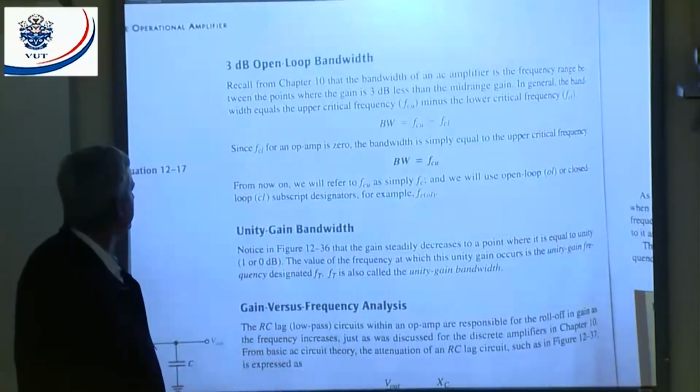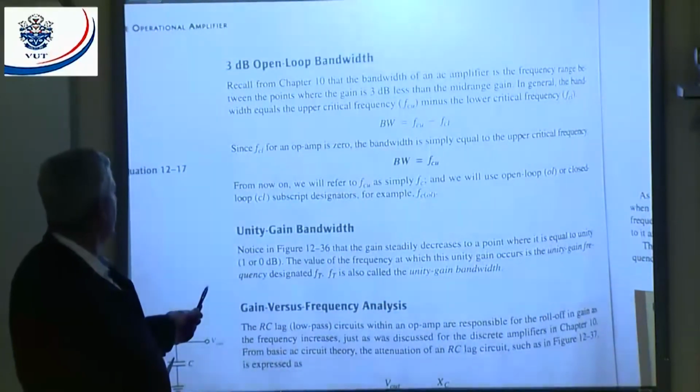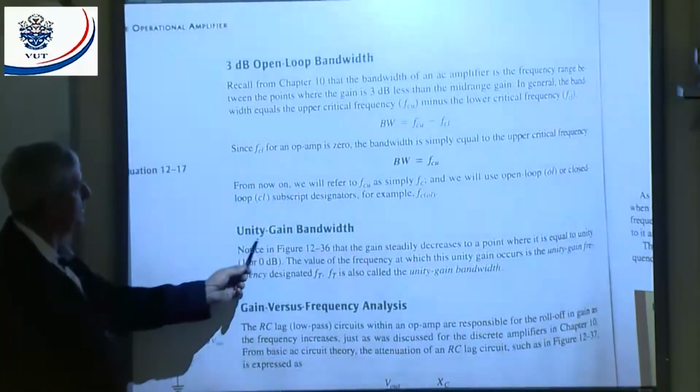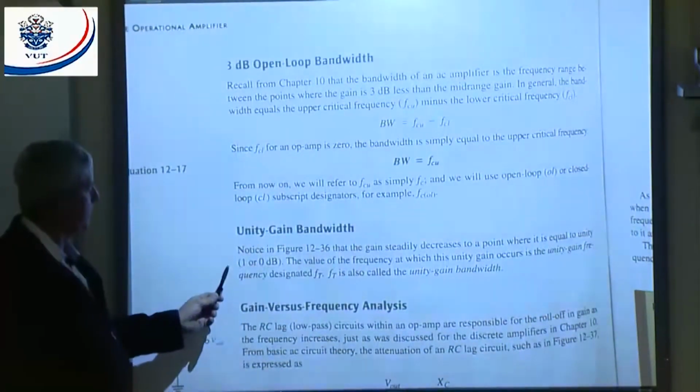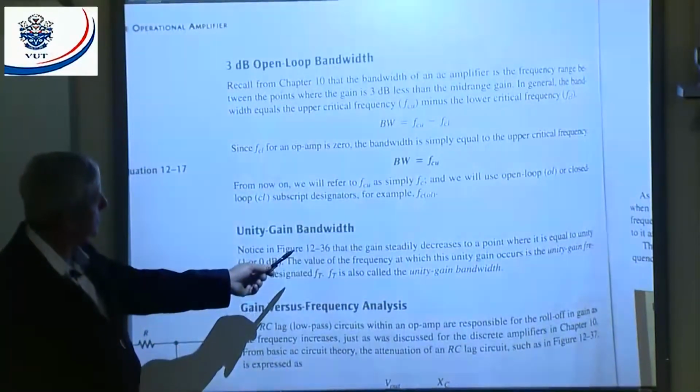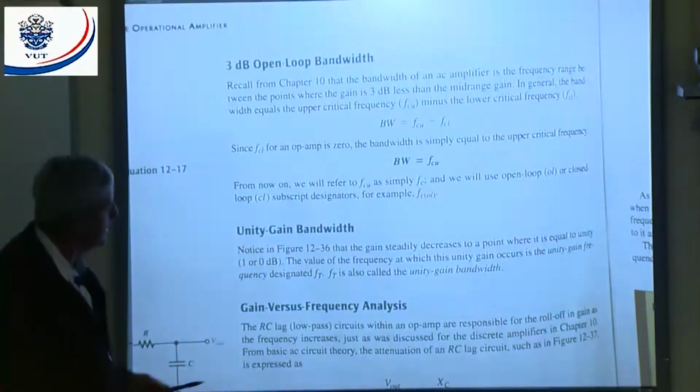Well, you can see there 0 dBs. There's 0 dB, all right? And that is 1, and there's my unity gain frequency, all right? And there is going to be 200,000 or 106 decibels. That means in a data sheet, they can give it to you in decibels, or they can give it to you per unit, all right?